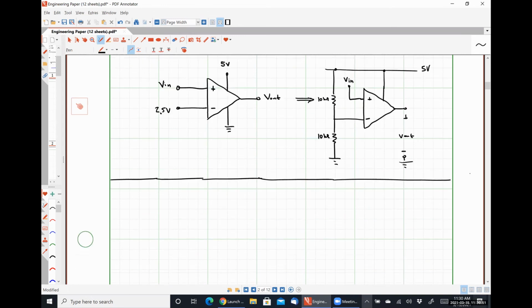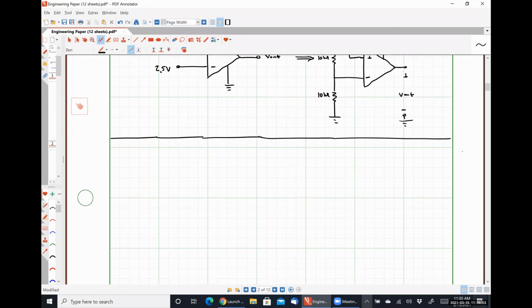So let's move along to circuit number 2. Unless anybody has any other questions that we need to take care of for the non-inverting comparator. Everybody kind of on board? If the input's greater than VREF, it goes high. The input's less than VREF, it goes low. All right, so our second circuit